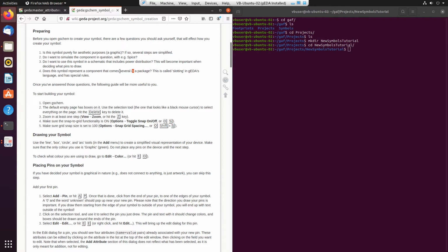So if you buy an op amp, for instance, you're able to buy dual op amps, quad op amps, or if you're buying gates, you're able to buy, let's say, a hex inverter, right? So one chip in a 14 pin package is going to have 6 inverters and 2 power pins. So that's what it means when you say several devices or several components in one package, and most often they're all identical components in one package.